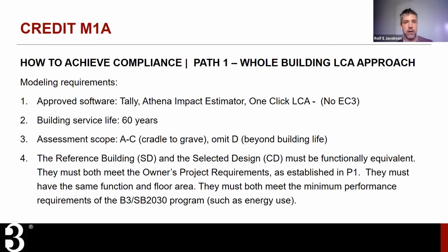Okay, so how do you achieve compliance with path 1, the whole building LCA approach? As I mentioned before, the software types that are allowable at this time are Tally, Athena Impact Estimator, and One Click LCA. So EC3 is not allowable at this time. Again, we are setting the building service life at 60 years. We want the assessment scope to cover everything A through C, that's called cradle to grave, and omit phase D, which is beyond building life.